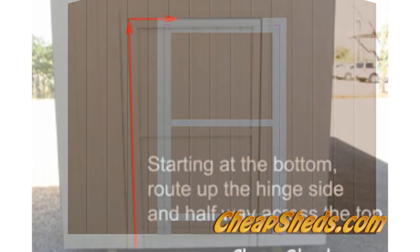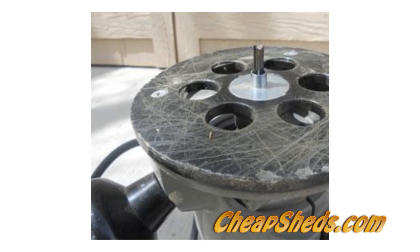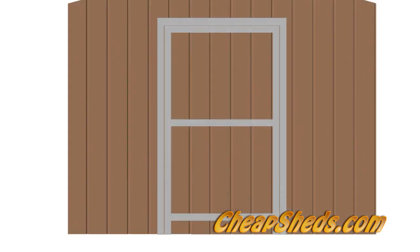Double check your spacing. In step 7, you will run a router inside the groove between these trim pieces and cut the door out. So double check that this spacing is correct by removing the collar from the router and running it all the way through the gap between the inner and outer trim. This will confirm the width is correct and the router will move properly.